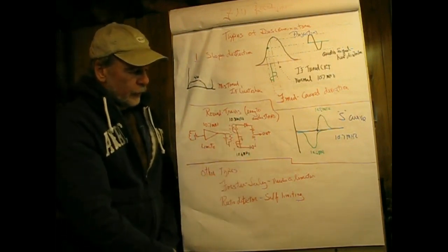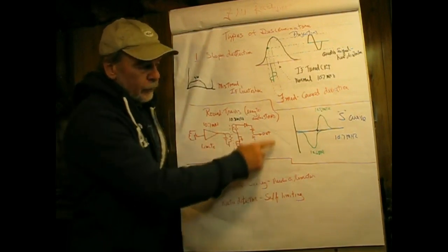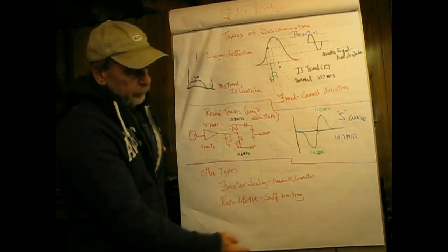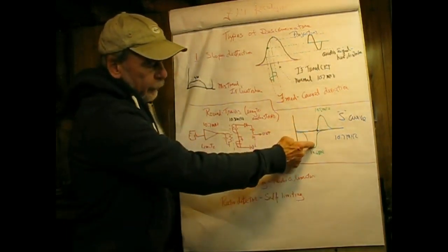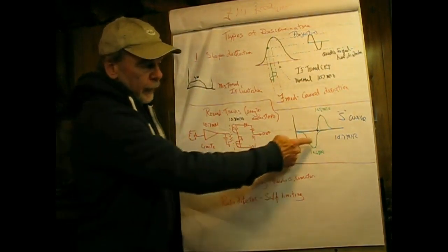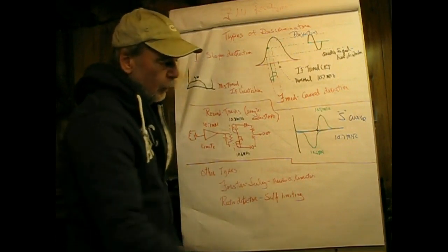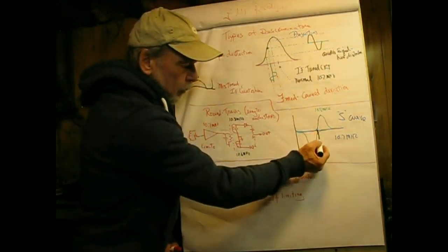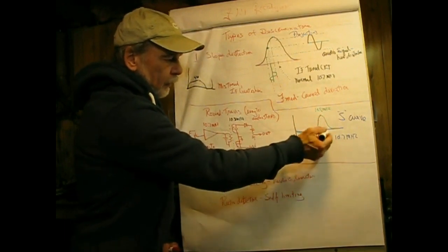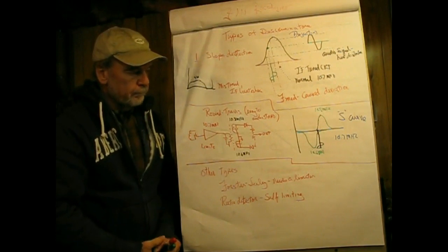And basically, if we take the superposition of these 2 tuned circuits, it kind of looks like this. Now, if I draw a straight line through this, that is what I want to do, is to have a very linear transfer curve. And then if I were to, say, do a projection on this, projecting that off the top and off the bottom, it would give us a pretty linear response.